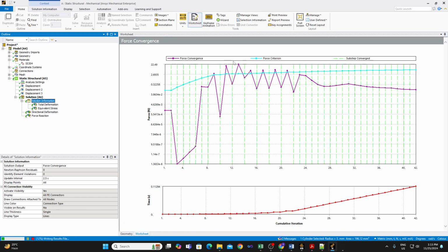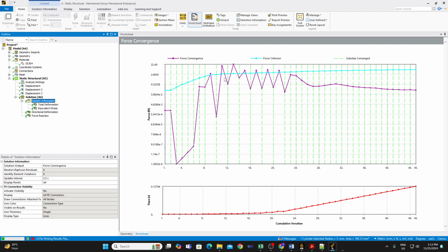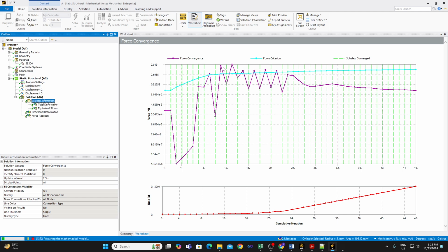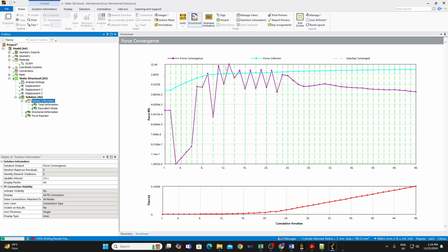so that even when the yielding is happening, which typically happens at the very beginning of the plastic deformation, or the very beginning of the solution, you can expect the time step is still small. So no bisection is happening, and that means the time step is not decreasing, and the norm is only going outside of the tolerance a little bit. Okay, and not a lot of iterations are required for the convergence.